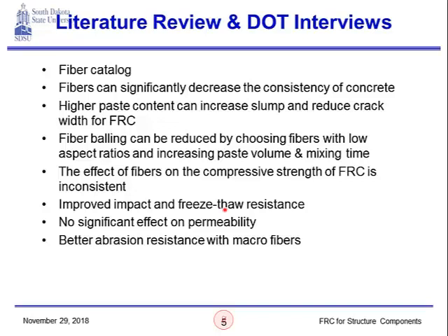Now, improved impact and freeze-thaw resistance was also noted in some of the studies in the literature review. No significant effect on permeability. There is one study that was looking into whether there's any effect on permeability once we use fibers, but that study showed no effect. Better abrasion resistance when we use microfibers.